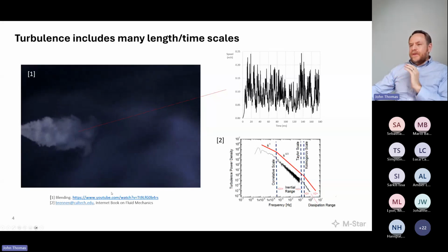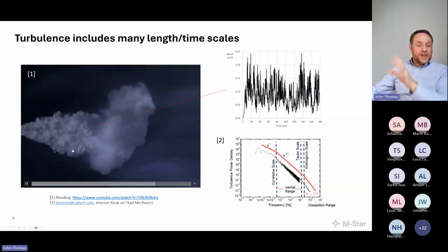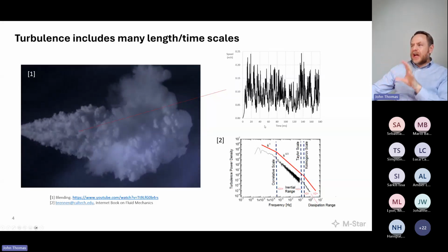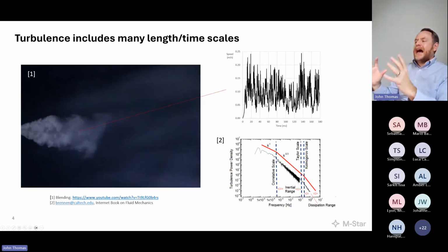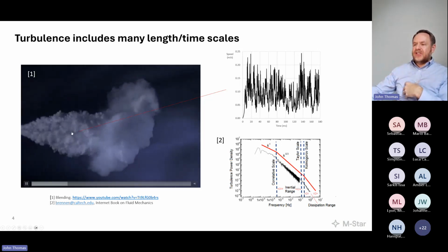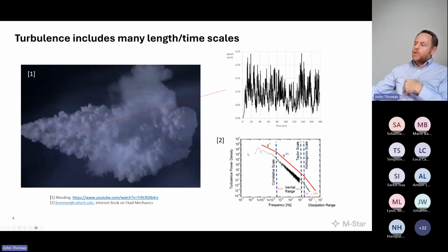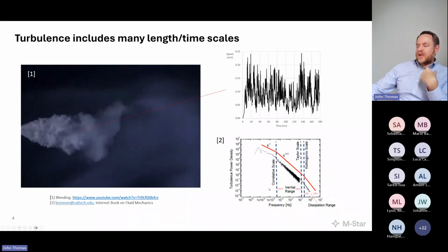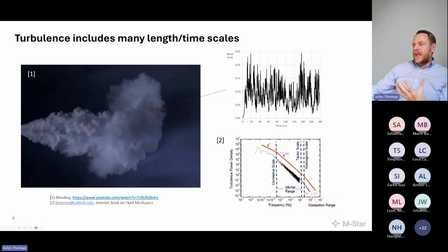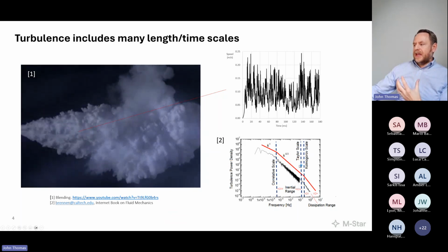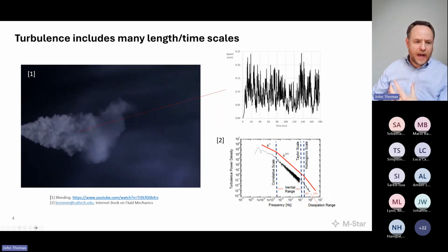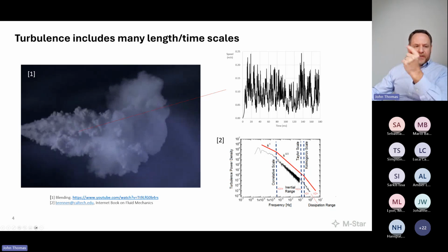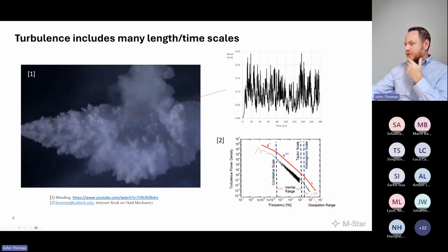So again, whether it's a flow through a jet or an agitated vessel, and I'll speak to this point in the next slide, these operators allow us to recast this seemingly stochastic system into reciprocal space with a well-defined set of repeating characteristics. That is a correlative integral scale, an inertial range governed by the Taylor scale, and a Kolmogorov dissipation range, where energy is being rapidly thermalized in this Kolmogorov dumpster.